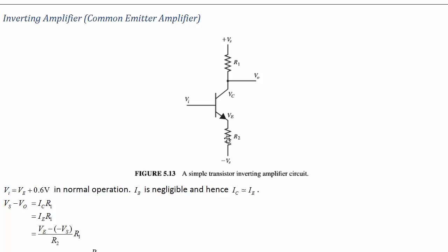Suppose R2 is kind of small. Then if we increase the voltage here a little bit, we could get a big current change through R2, and that's going to pull a lot of current through R1 as well. So if R1 is quite large compared to R2, we should have a big change in the output voltage from that change there.